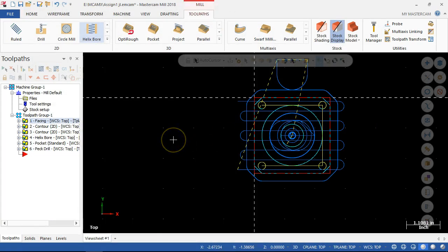You set an incremental step for the helical moves. Will it then just provide a loop? Typically, the incremental is telling it to start or stop in relation to the wireframe, so that you're not stopping the rapid at the 1 inch above. I can rapid it all the way into that pocket if I set an incremental move that says it's 100 thousandths off the bottom of that pocket. But I'm responsible for making sure that material is gone when it rapids.